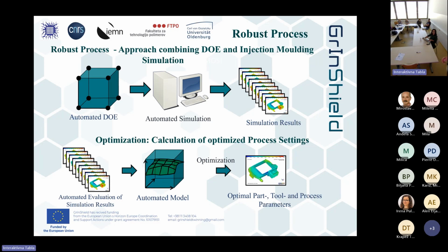And finally, they wanted to know which machine settings in terms of mold temperature, melt temperature, pressure, packing time, and so on. Which settings do I have to choose so that my part will be perfectly produced? I do it in the computer. And with all the knowledge which I told you, you know now it can't be exactly the reality, but it can be close to reality.